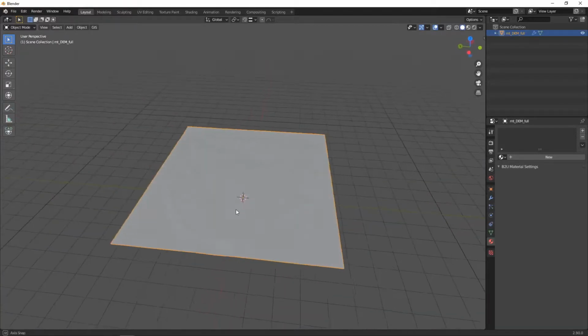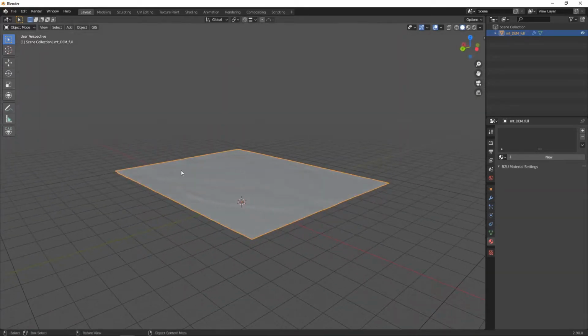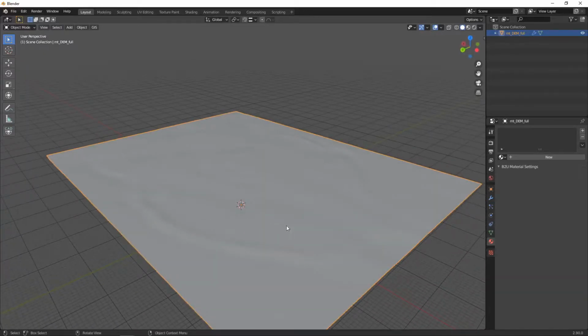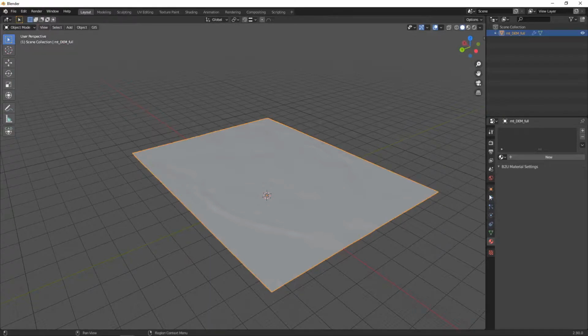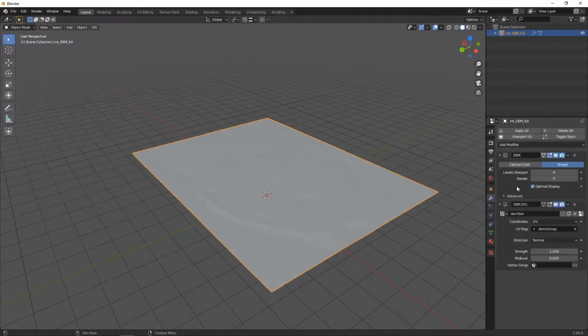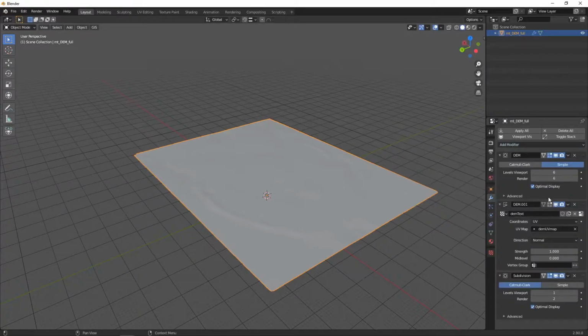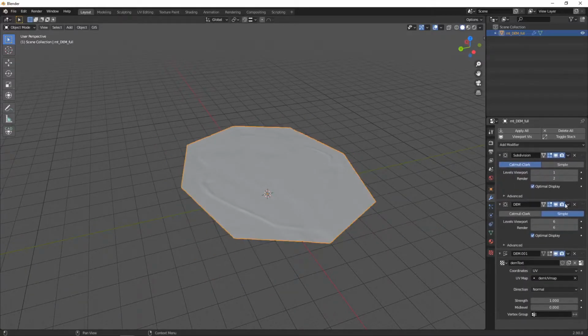Import it. As you see, we have the same problem as in the previous video. The digital elevation model, or the mesh that's created, is of relatively low resolution. And we know now why this is. This is because of a setting and the modifiers. So in order to create a higher resolution mesh, you simply add multiple subdivisions on top of the already present one.